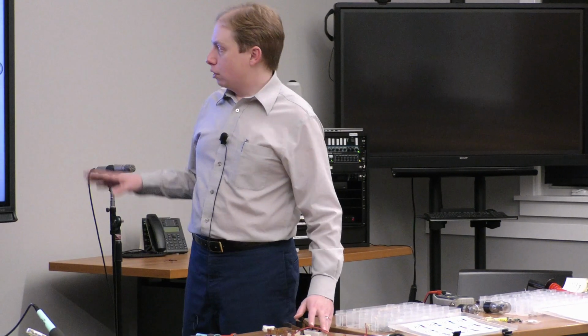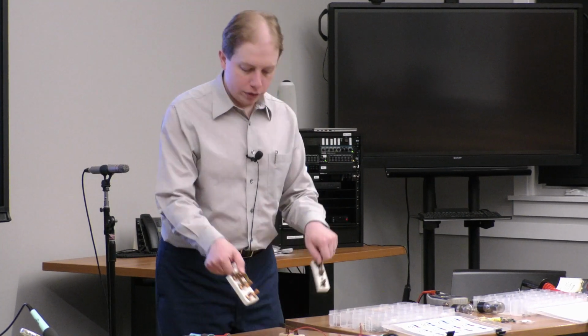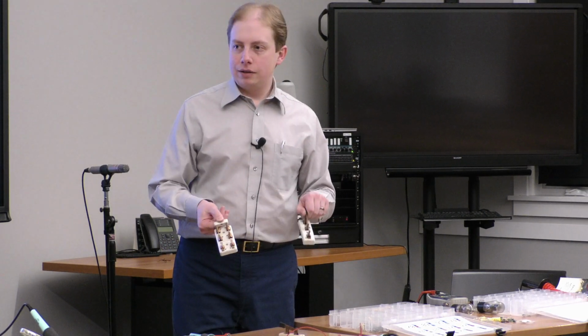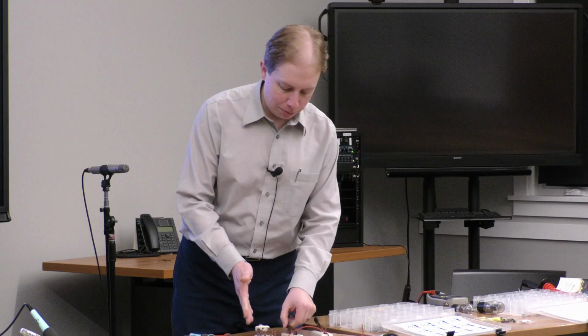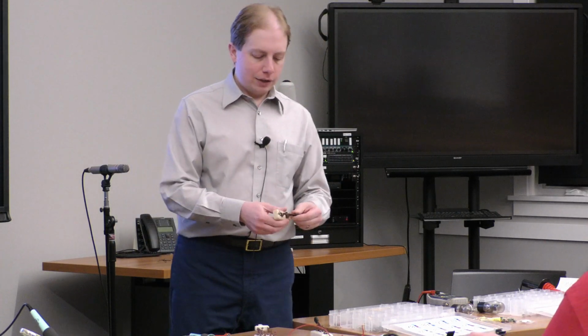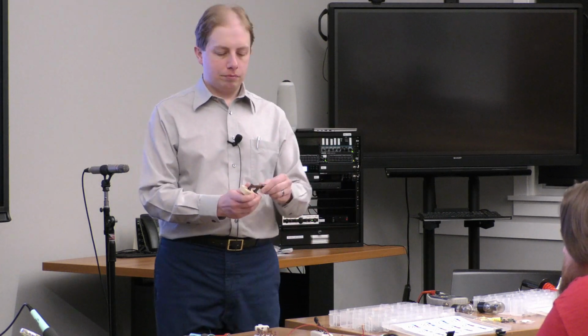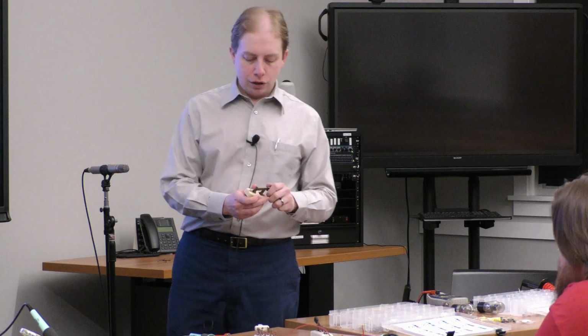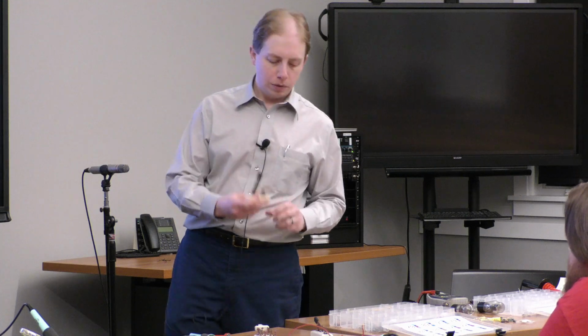All right, switches. You have to know this terminology for the test. So I brought some old knife switches because it's really easy to understand these terms if you can see them set up like this. So a basic light switch is on and off. You have one pole, you have one blade here, and you can only throw it one way, to one contact. So this is a single pole, single throw switch.